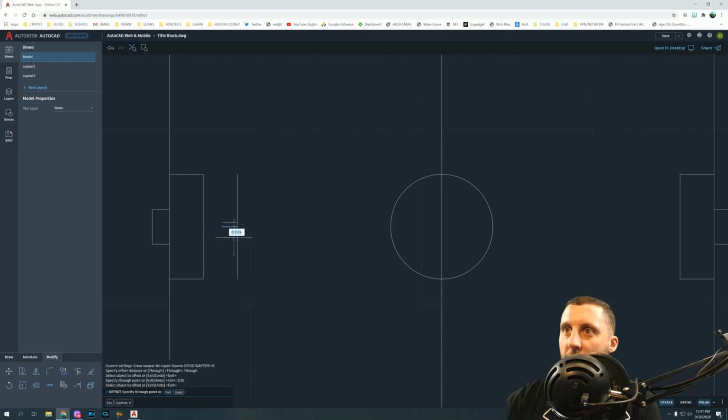And then I'm going to grab this line again and go 1/16 down. Now I can get rid of the middle one, and I can trim. So without those 2 dummy lines, I wouldn't have anywhere to trim it off at, and that's why we need it. And then you get rid of these 2, and you have your PK line.